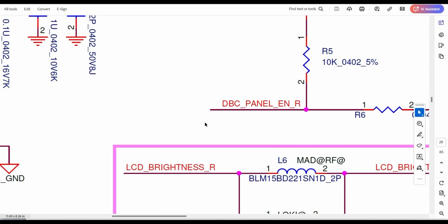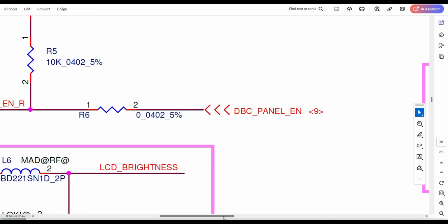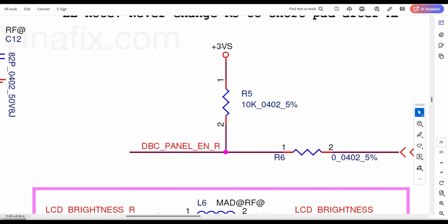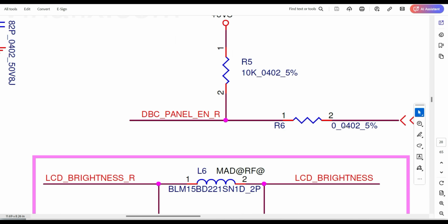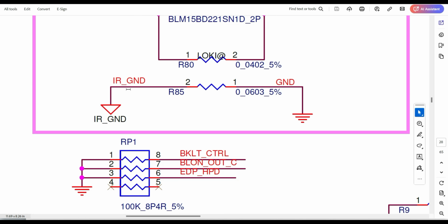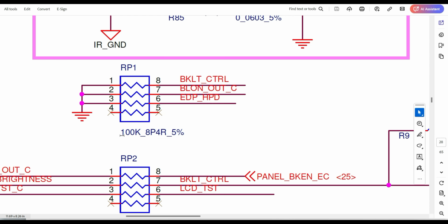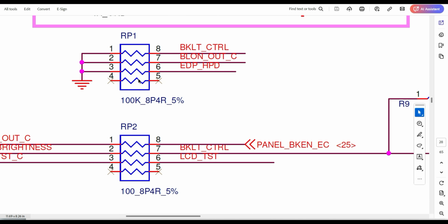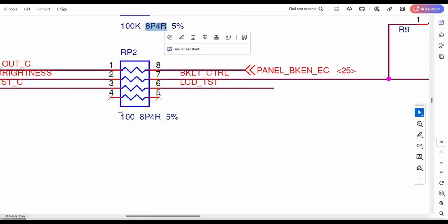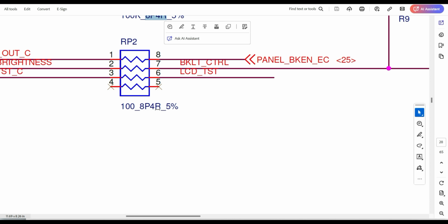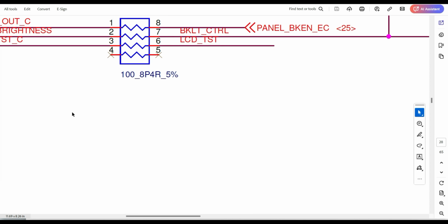Here this is the voltage divider; it depends on the source. See, if this one is connected to the ground, then here you will get a voltage divider. Otherwise, here what voltage, 3 volts, only 3 volts you will get. Ground, both sides ground. Here is the pull down; the network resistor is going to pull down. The size is not mentioned here, this is the size actually. Network resistor, 0804.